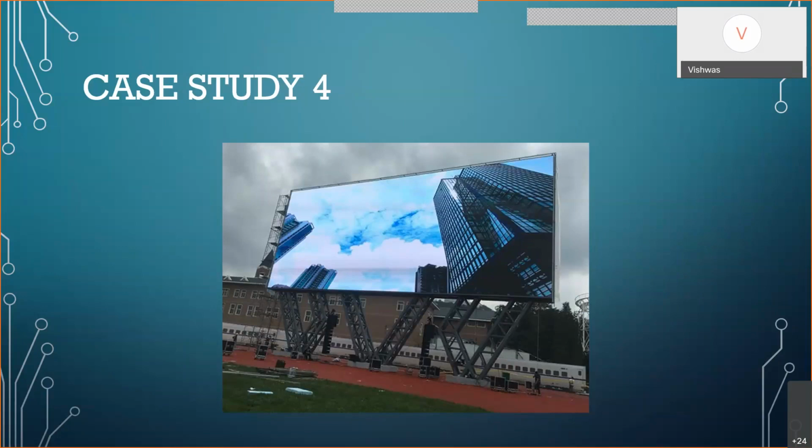It's like your phone having individual pixels. Just like that, it will be a whole bigger display with multiple matrices. Each matrix will cater to some rows and columns of the LEDs. For example, let's say each individual matrix has 100 LEDs, then it will have 10 rows and 10 columns. If you put 100 such matrices, you will have a very big display made of a lot of small LEDs. So that is the thing.